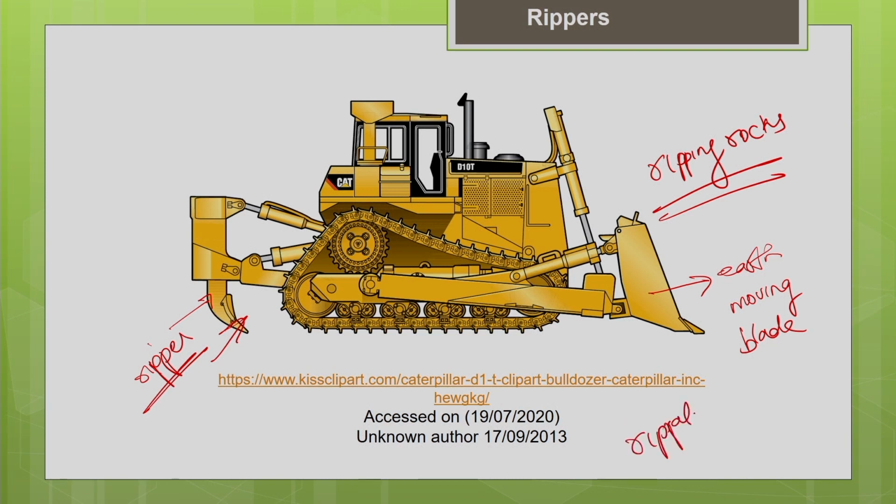You have to check the rippability of your rock. For that, there are some special methods like seismographic techniques. We are not going to discuss that in this particular lecture. Based upon that, you can check whether the rock is rippable or not. Once you know that the rock is rippable, you can use this technique for ripping it. That will result in huge saving in the cost. Similarly, you can also use it for ripping old pavements, so it can have different applications.